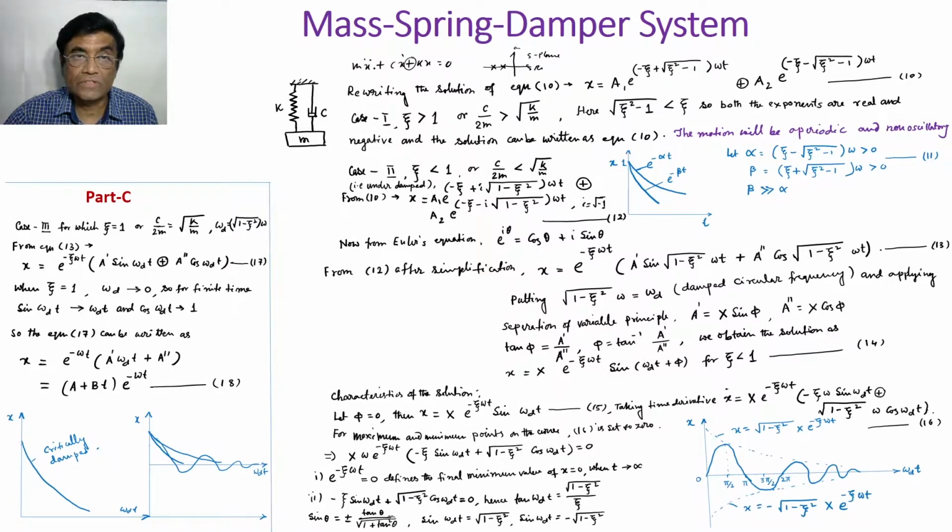As long as this is positive, roots will always lie in the negative domain in a second order mass spring damper system, which ensures that if I can design a controller with such a root, where the root will always be traveling somewhere here, and I design the gain parameter, then I can prove that my controller is asymptotically stable.